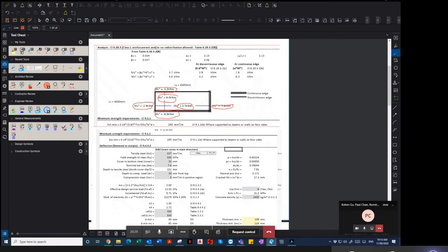Even if it supports a 360 UB and it's 7 meters long, we know that it will work. But as soon as you are putting a 500 UB, something like that, then it would prompt you to check the column because the loads are a lot higher than what you would normally use. Make sense? So in a simple way, this calculation will do the same too.